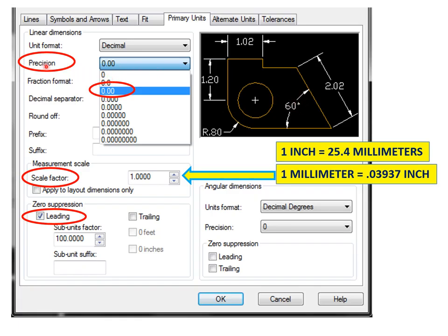If you also want to change the number of decimal places, you go to Precision, go to the drop down, and if you're creating an inch drawing, so a drawing with units of inches, you typically want to go with 2 decimal places for all dimensions. If it's a circle where you need precision, accuracy, then you may go with 3 decimal places or 4 decimal places. But for inches, typically you go with 2 decimal places for all your dimensions. And then from there you can deviate. You can go to 3 or 4 decimal places if needed. Remember, the more decimal places, the more accuracy, the more expensive the part gets.